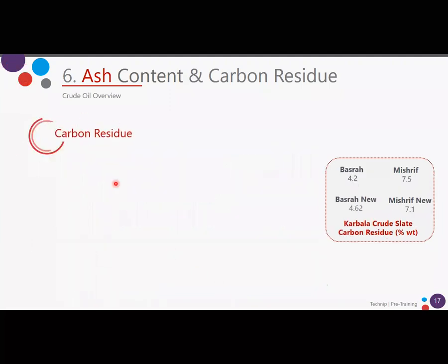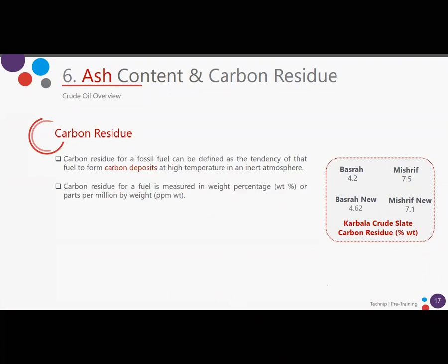So now we will see the carbon residue. The carbon residue, for a fuel, can be defined as the tendency to form carbon deposits. In this case, it's at high temperature in an inert atmosphere, okay? Carbon residue for a fuel is measured in weight percentage or parts per million by weight, milligrams per kilogram.